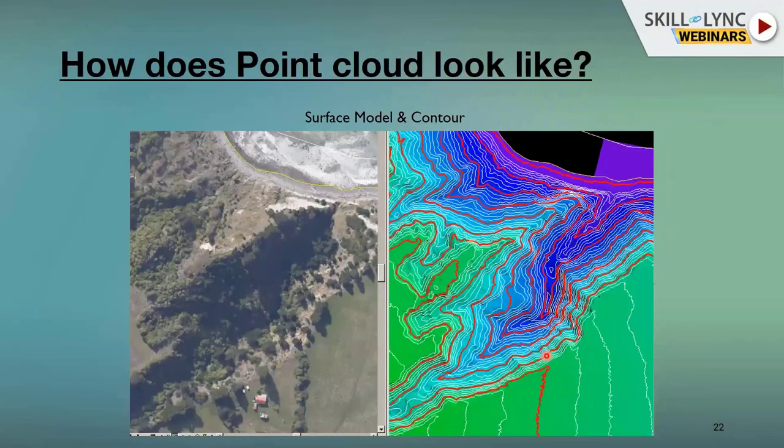So then the point cloud data, after generating the orthorectified images, after generating the DSM. So what does it mean, the DSM? As I said, the point cloud data will give each point's XYZ information, right? So I just want to see the real world surface models. There are some options in the software, like I just want to create the surface model.